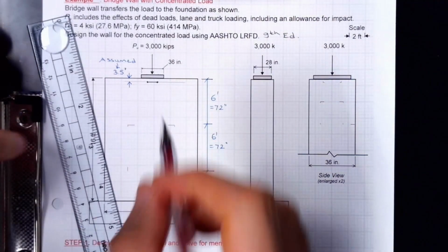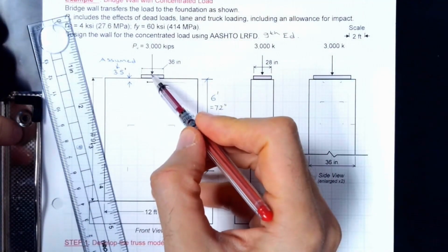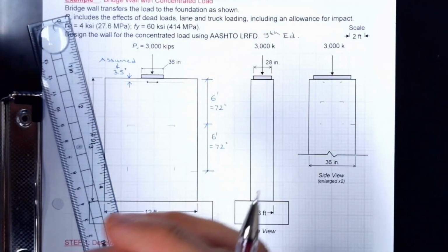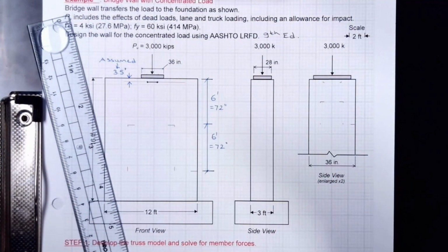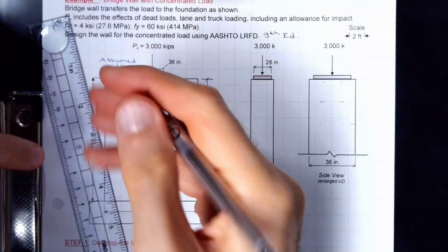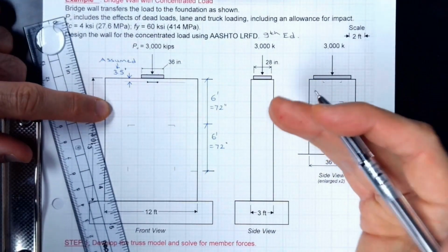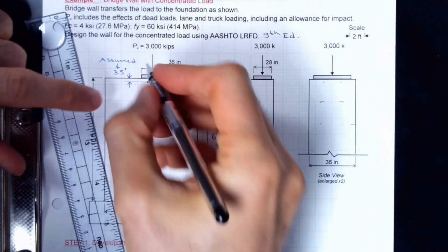The other important aspect in any strut-and-tie model, if you have a load applied to a location and if it is spreading, you want to separate that load to create 2 different nodes. This makes the model more efficient, it makes it more realistic, as well as it makes checking easier because you separate it into multiple nodes.